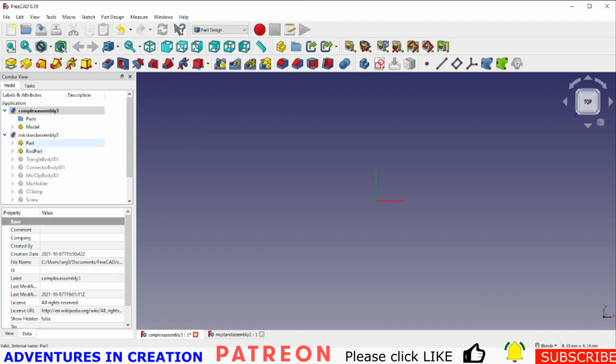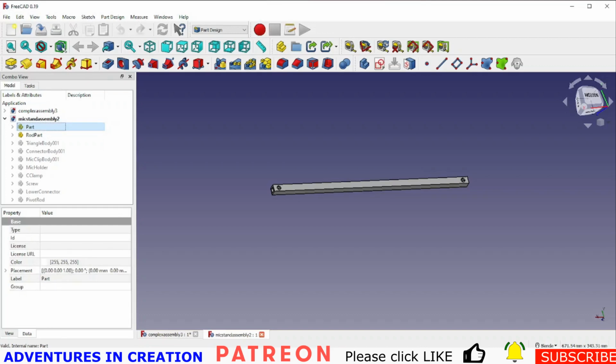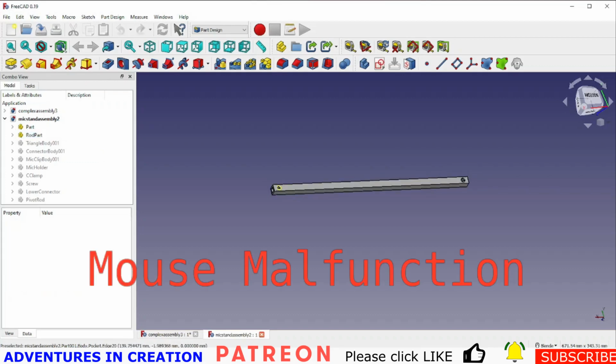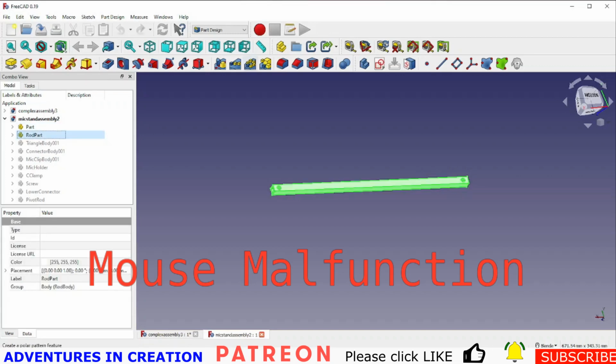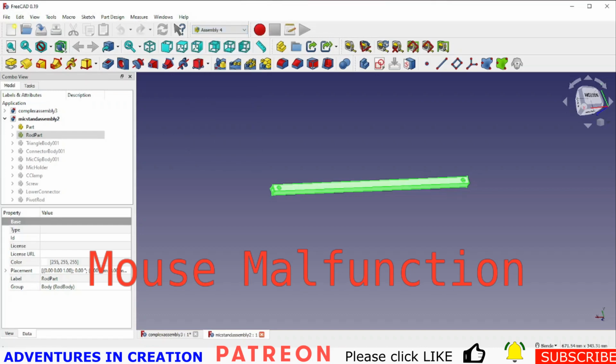Okay, now we need to take the parts. So I'm going to make sure my mic stand assembly is the piece that has all my parts, and I've created all these parts inside it. Remember, I just took the bodies out of the one that was just called part, created new parts, and put all the bodies in the subsequent parts. So now what we need to do is create some LCSs that we can assemble these parts with. So I'm going to take the rod part. I'm actually going to go back into my assembly 4 workbench.